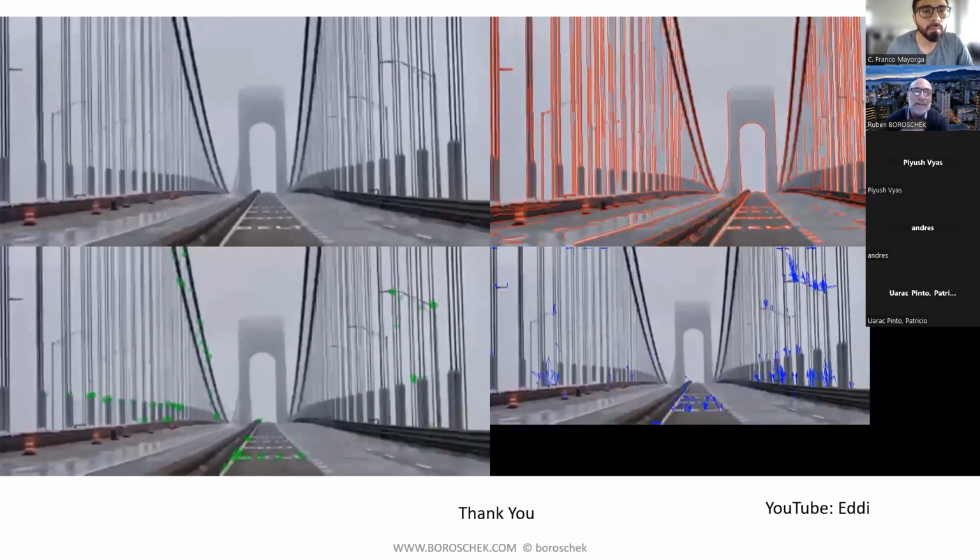Now, is this a fixed value? Definitely no, because, for example, in buildings, we do notice changes if we monitor during operational hours, for example in Chile, from 8 a.m. to 6 p.m., and at night, because we don't have the human loads and other type of operation, we have higher water tank levels on the top of the structure, or the use of the elevator changes the period. So we never try to put more than 3 decimals. Actually, we try to work with 1 or 2 decimals if we are working on frequency.